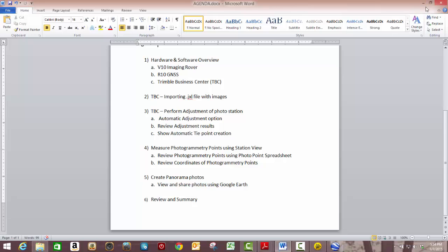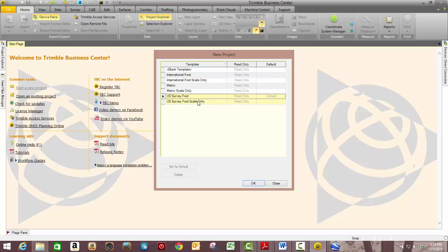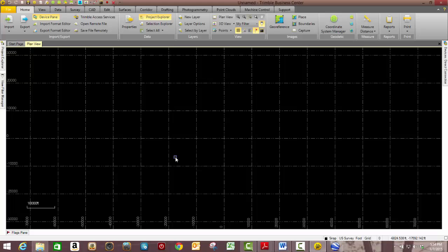So with that, let's move on to Trimble Business Center. What I'm going to do here is go ahead and start a new project. I'm going to use a US survey foot template and create that project.